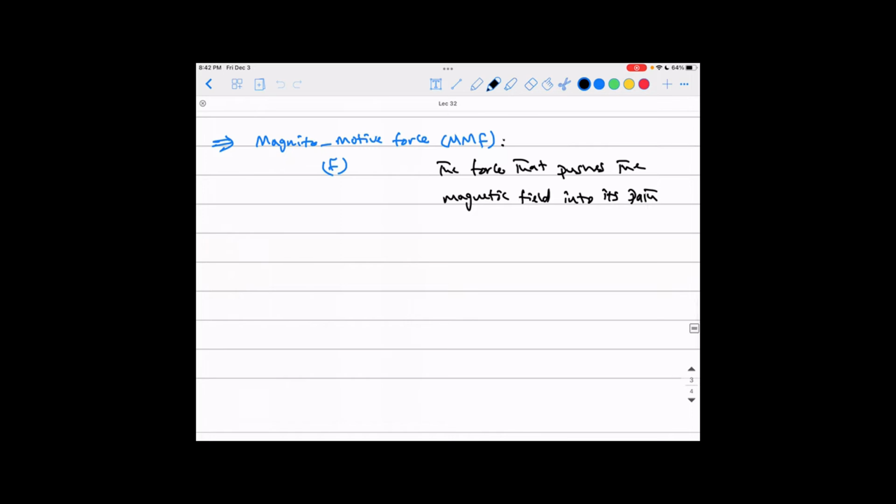Okay, how to calculate it or how to derive it is not our main concern actually, but it will take this form. F will be F as a magnitude, sine omega e t, which is the frequency times time, multiplied by sine P over 2, where P is the number of poles, multiplied by theta mechanical. Okay, this P is the number of poles. That is the mechanical angle.